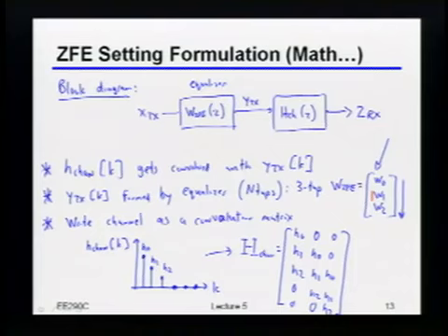Yeah. But is that enough to represent the channel well enough? Okay, so that's a great question. We're actually going to talk about that a little bit more later. From the standpoint of the data, that's sufficient to get the Nyquist frequency of the data. Okay, because if I have 10 gigabits per second, the fastest the data could be doing is 5 gigahertz.